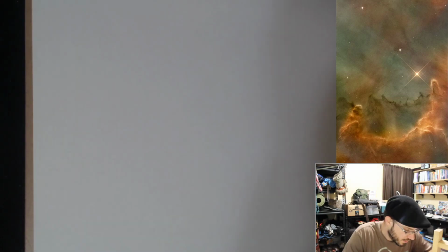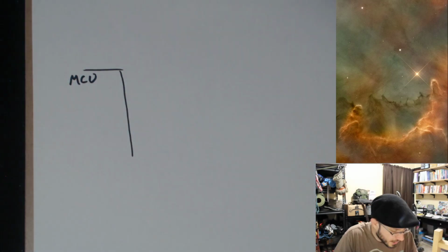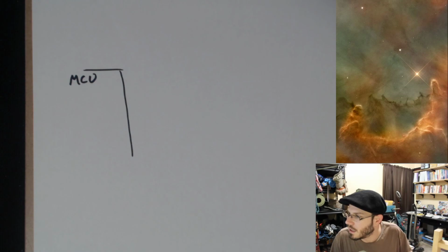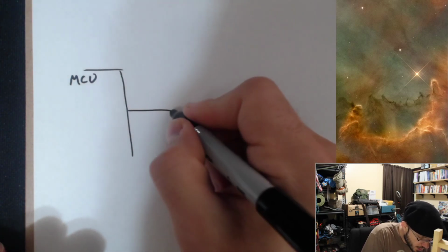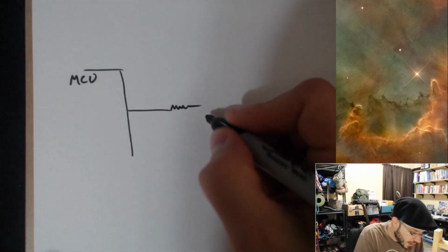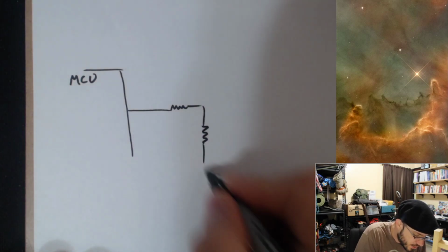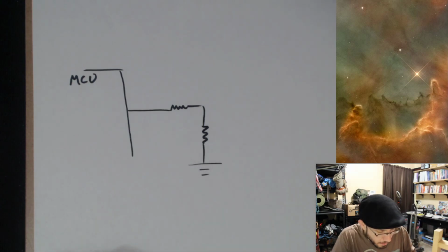Okay, so let me go ahead, draw, and put all of this together. Everything we've talked about thus far, for a very common application that you would do when you're making a little robot project in 346 or 347. You're going to be using some microcontroller. You're going to put some resistor to limit the inrush current. You're going to put another resistor over here in order to safely discharge the MOSFET.